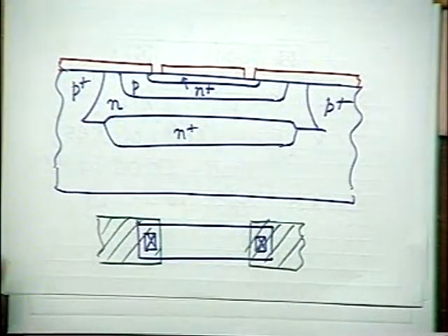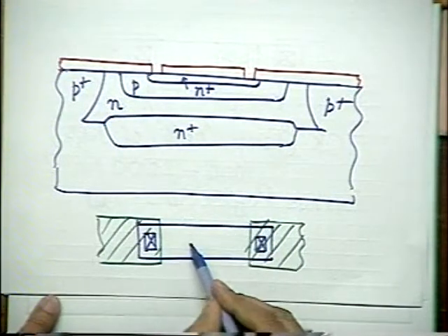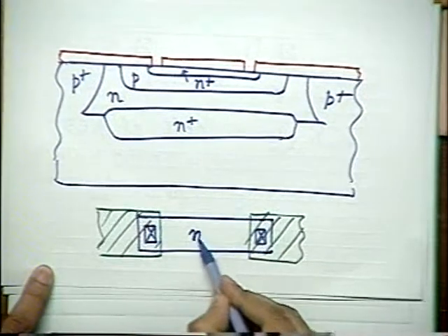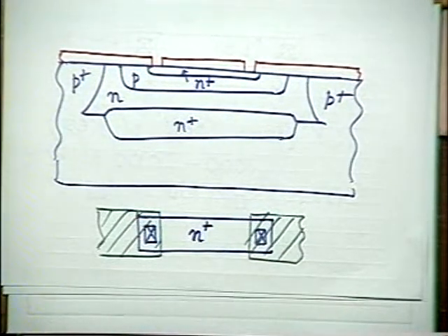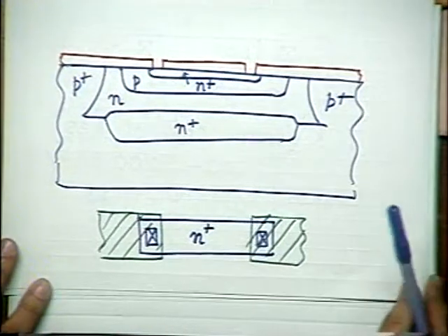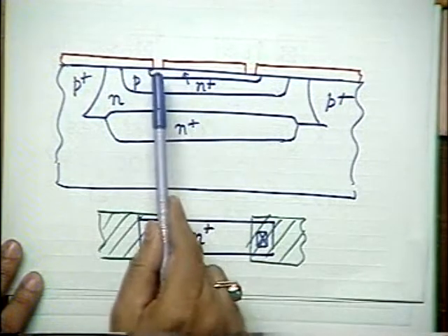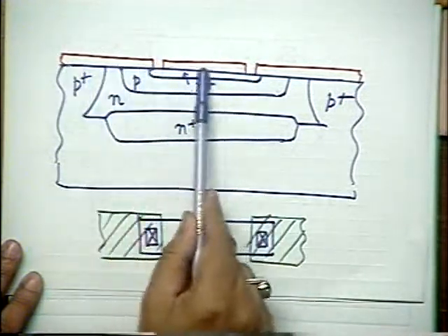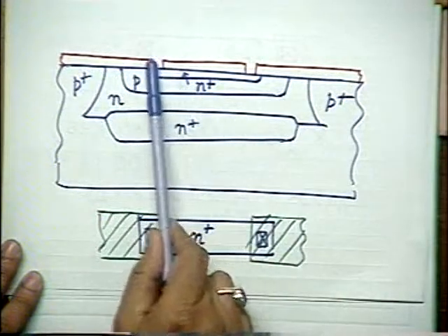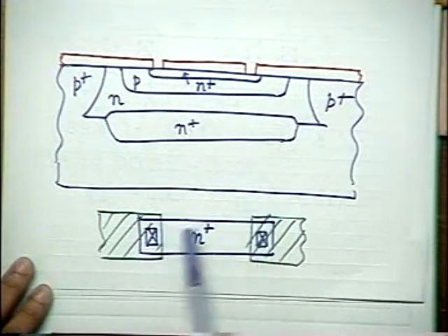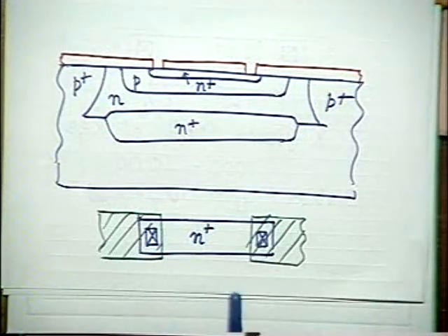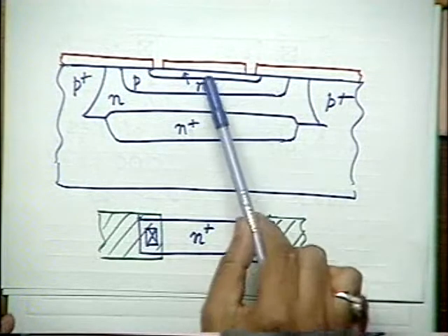What is the problem of this resistor? This region, please remember, this island, this resistor has used now N plus emitter region. It's very strongly doped, has got a sheet resistance around 10 ohms per square. So I have metal contact here and here. The red region is oxide. I have metal contact here. I have adjusted the length to width ratio such that I get the 30 ohm resistance, 10 ohms per square being the sheet resistance of this emitter, for example.